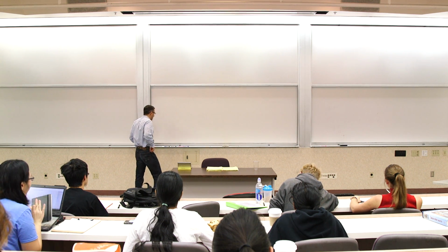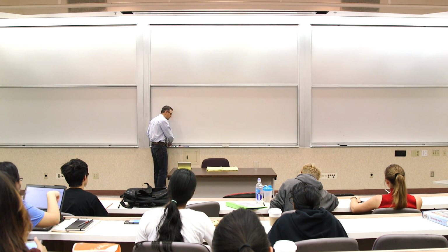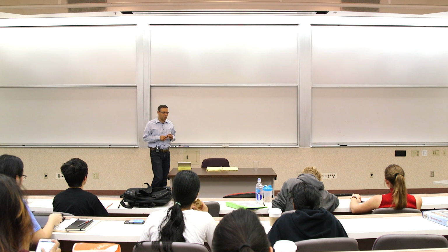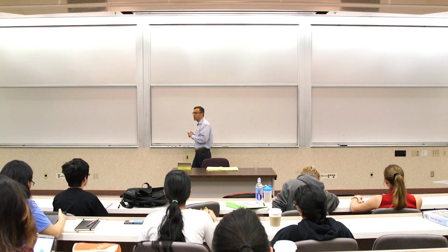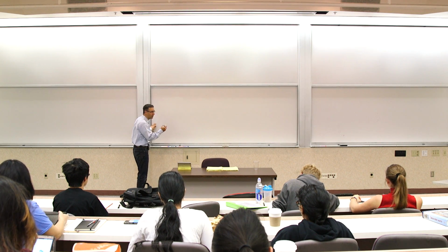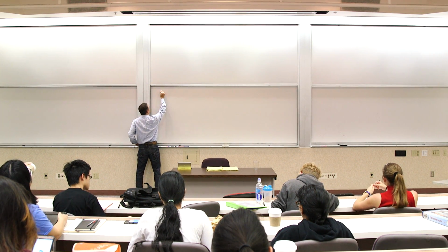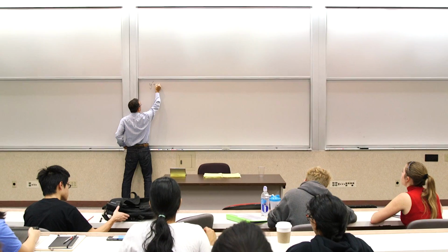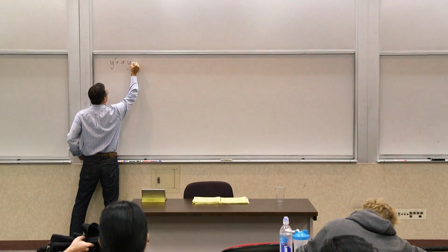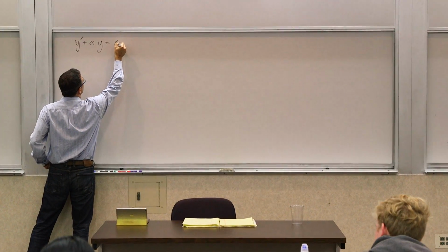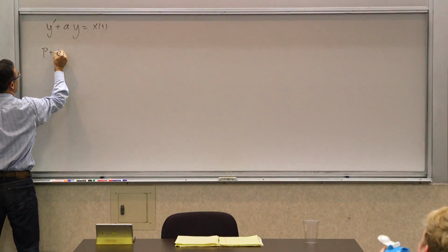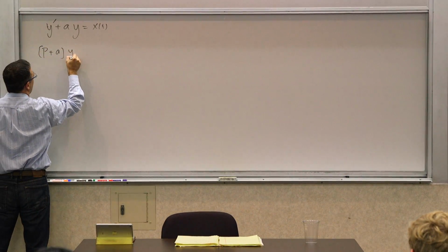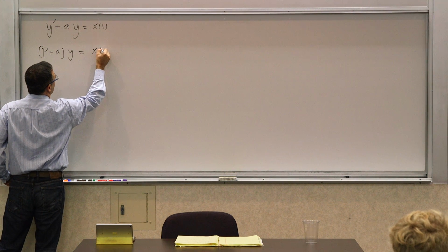Well, good morning. Last lecture, we developed this inverse operator for the first order low pass and the Heaviside operator. What we did essentially was to look at this differential equation, y prime plus ay equals x of t. We noticed that you can also write this in terms of the Heaviside operator as p plus a operating on y producing x of t.